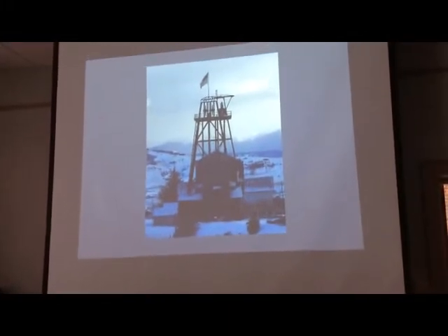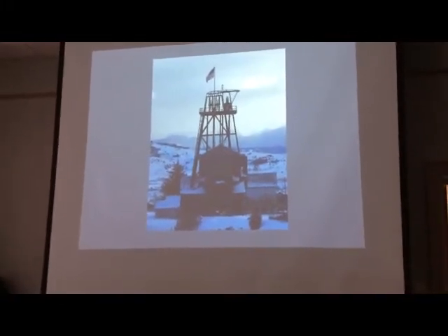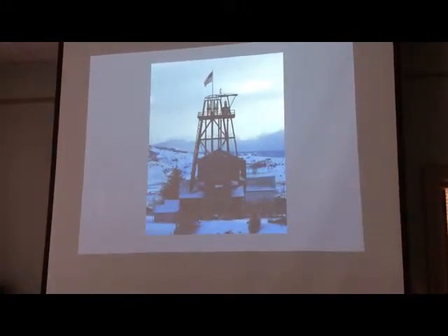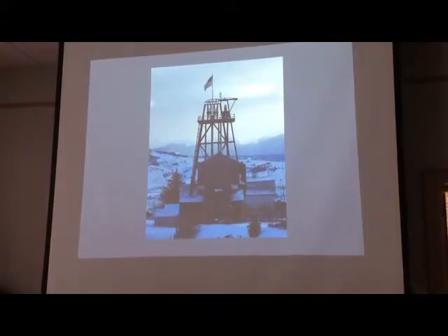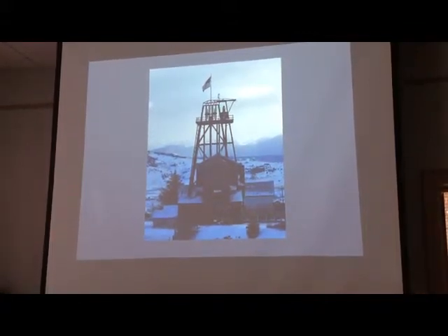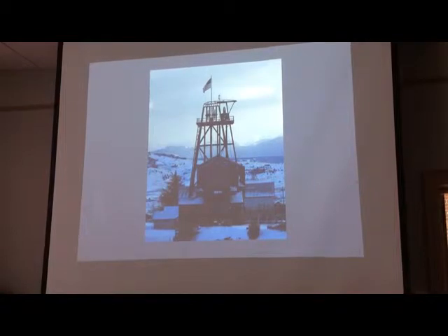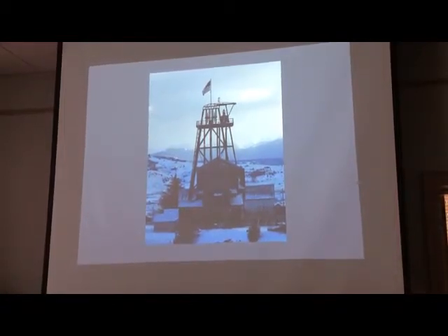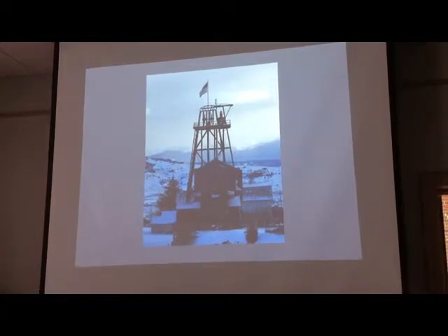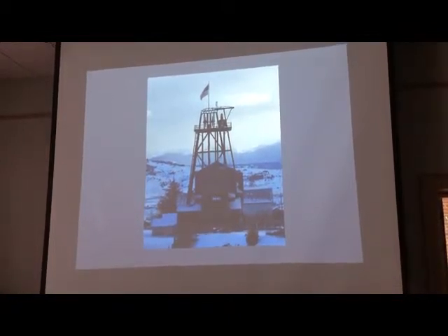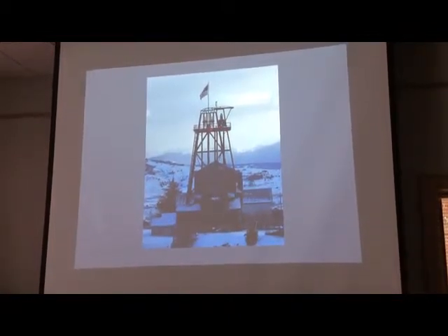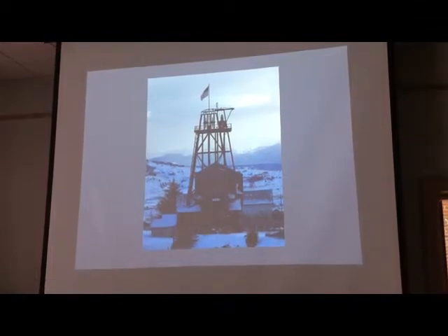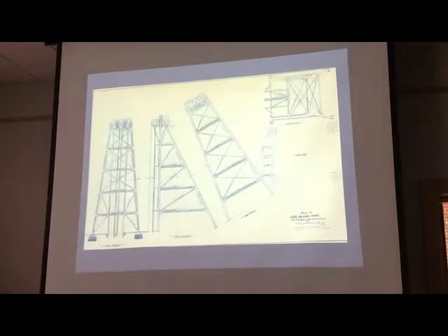Well, I took a look at this because I was going to try to trace it, you know, we can trace it back so far but not further. But this is an 1890s design. Gillette Herzog, you can see the crown of the arch as their distinctive design on it. Post-mount sheave bearings, 70 feet in height, nothing particularly huge. This, of course, was the addition that was put on in the 30s of rolled steel with girder mount sheave bearings. So I started looking back through the designs.